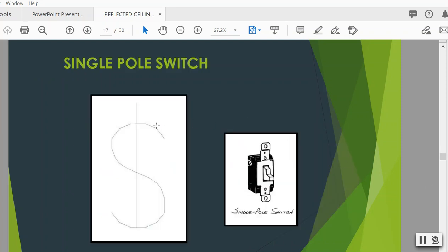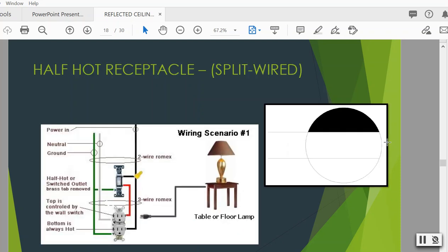Now remember our switches. They look like a dollar sign, but only one less line. So I want to let you know, you always do a switch where the wall is here and it's sticking out this way. So wherever the wall is, you must put the line and that perfect little S, and that represents a single pole switch. Some of you were putting the S next to the wall, but it actually really needs to be connected to the wall right here. And that's a single switch.